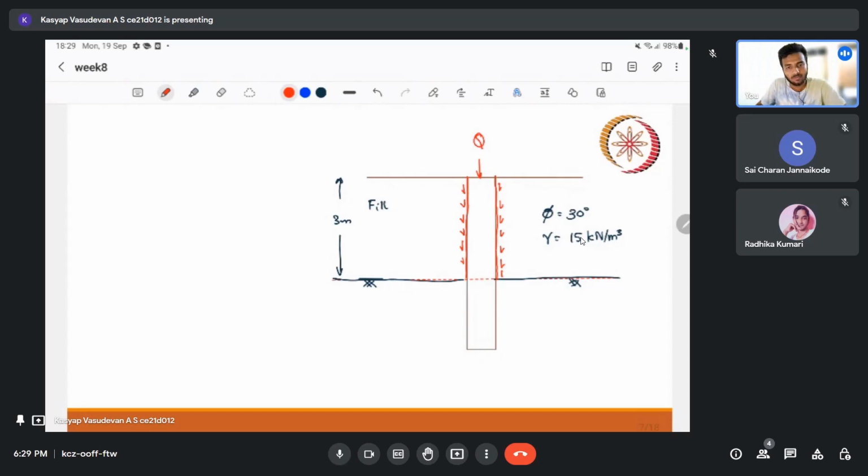So whatever we are calculating for the superstructure, we have to add this, right? For resistance, we have this lower portion. That is the catch here. Only the lower portion is providing the resistance, and if it is end bearing also, we have to show.